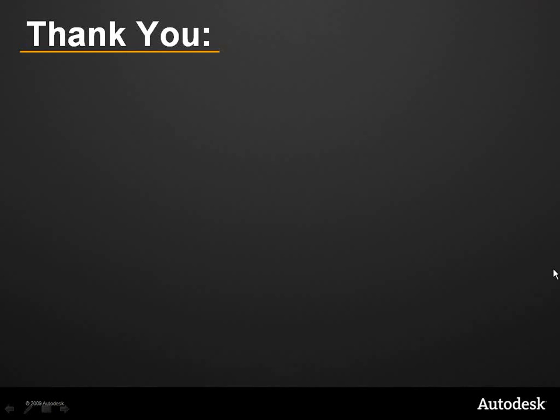But it's quite simple. You can put a couple points in a drawing and then scale your image to it, and then use things like our Raster Design, if you like, for auto vectorization. Or you can leave it in its native state, use it as a backdrop, and where you see a visual issue with a raster versus vector, then you could vectorize. So you wouldn't have to vectorize everything.